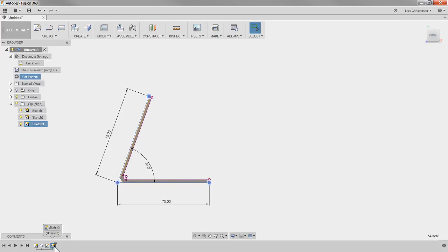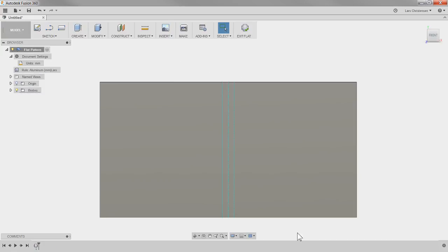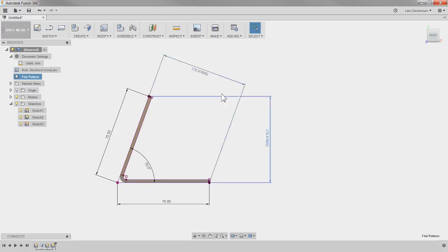You will take your dimensions again and see if you can get closer. You will bend it again at 0.35 and then measure again until you get the right number. I hope that makes sense. So you will flatten this out. Now that we changed the K factor to 0.35, this number is different than when we had it at 0.3, right? So you will take this number, cut that little piece of material out, bend it up on your machine, and recheck these numbers to see that you're getting closer. That's a way to find the K factor.